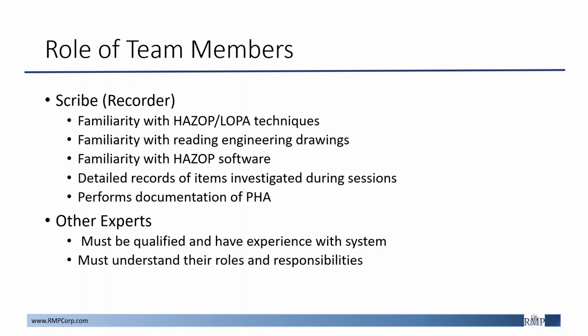In most cases, the financial threshold for when it is more convenient to use a scribe is once the team, excluding the facilitator and scribe, exceeds about 4 individuals for a local project and 5 for a project that involves more facilitator travel costs. When a scribe is included, they are expected to be familiar with the HAZOP methodology to ensure that they can properly prepare any documentation and be effective at all times during the sessions.